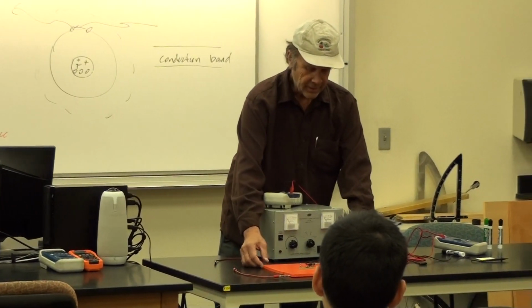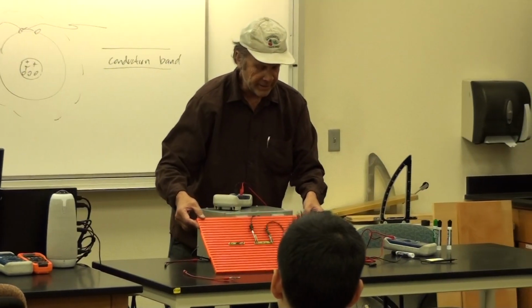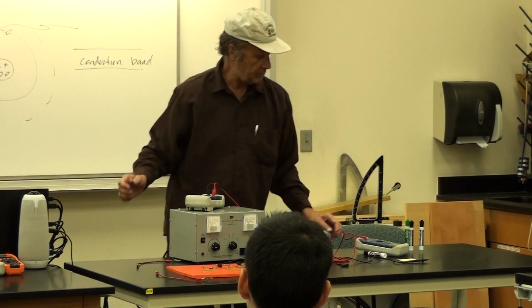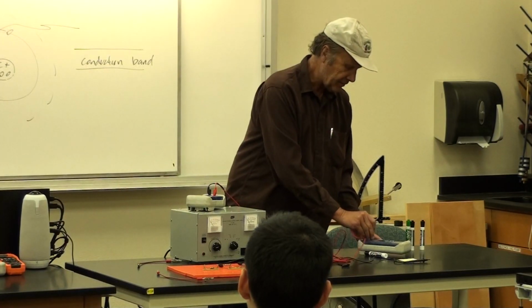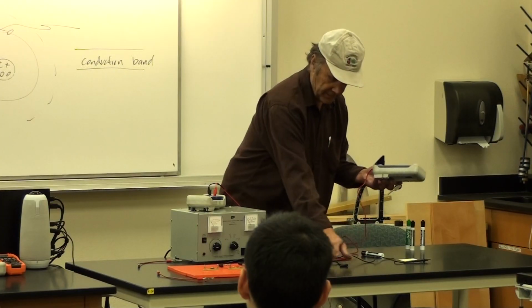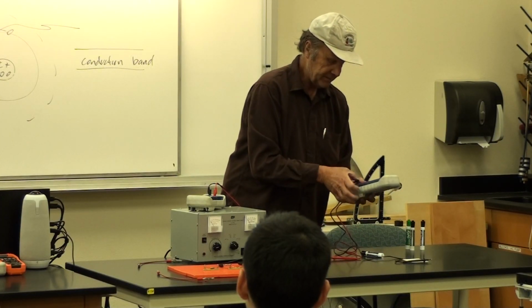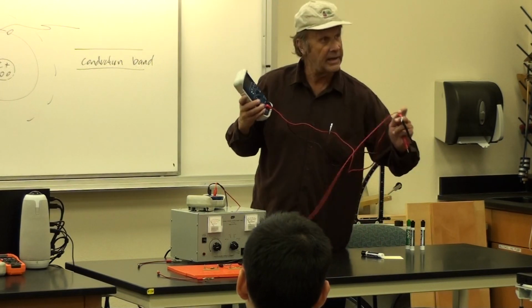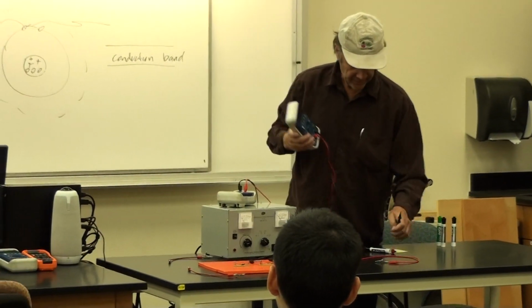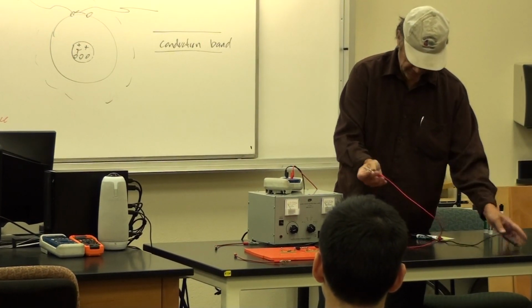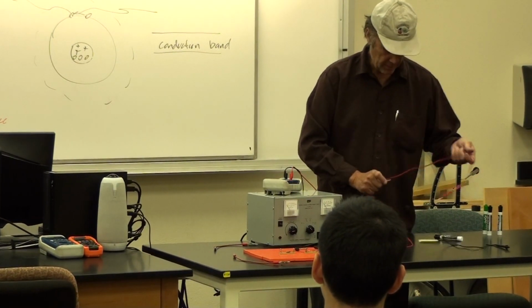We've got our circuit set up like this, but in order to measure the current we need to get the meter right in the flow. We've got positive and negative, so the hot side comes out like this and connects to the hot side of our current meter.